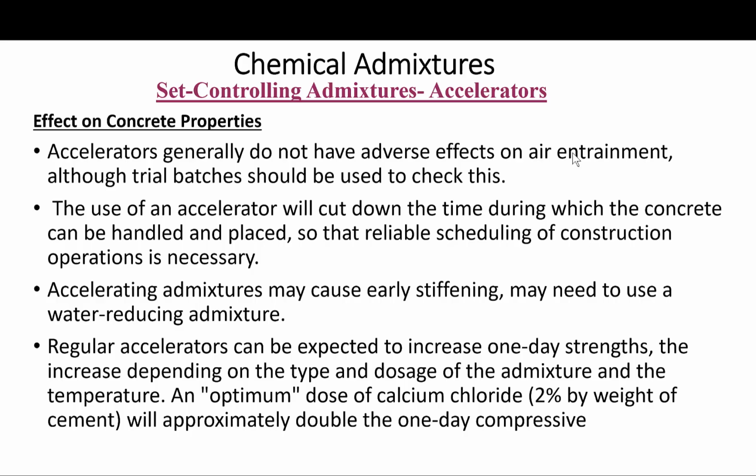Also, accelerating admixtures may require some additional water if early stiffening occurs. But this is just a general statement. Nowadays, they can be formulated with a water reducing admixture, so we will not add water.